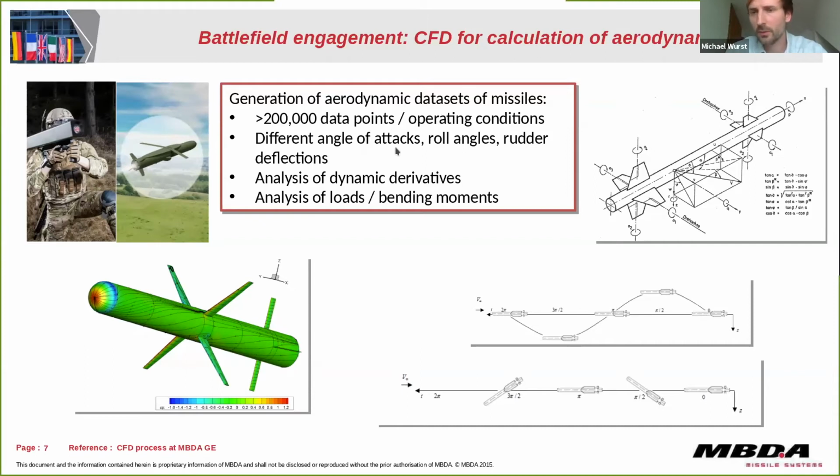What we also do here with our CFD solver is that we analyze the loads and the bending moments, for example, here on the fins, and that can be used for further structural analysis. And what is also sometimes done here is that we analyze dynamic derivatives like pitch damping moments. This can be done if we give a sinusoidal movement to the missile and analyze the coefficients then. This is our standard business, I would say.